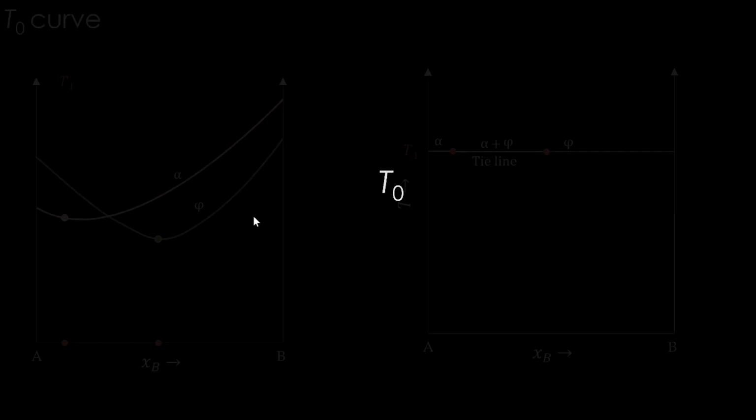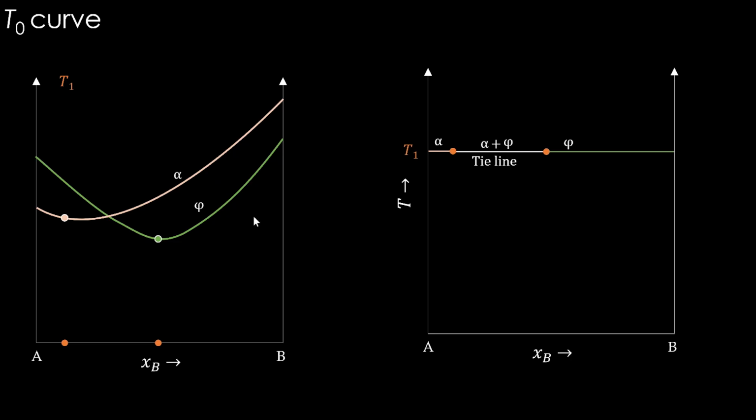So now we will look at what is T naught. This is another important idea to understand some of the phase transformations. This is a temperature T1 where we have two phases intersecting like this, and we take this composition to the phase diagram and plot tie line information like this. We get the entire phase diagram by repeating this at multiple temperatures. You know that story. Now the point is, look at this point here.